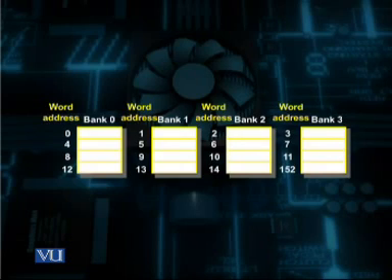And it permits a read or write of a word at the same address of all the banks sequentially. That is, the interleaved memory is logically a wide memory, except that the accesses to banks are staged over time to share the internal resources.